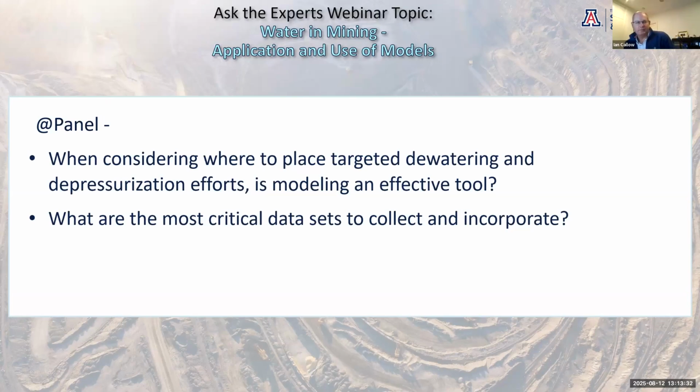Well, from my perspective, it really comes back to the conceptualization, right? Which I know Jeremy and Jeff are very keen on. But without that conceptual model, it's a bit blind. And so the data sets, in my mind, are very much the structural model, and any monitoring wells, piezometers you have around that, and their responses will dictate just how effective your depressurization efforts are and where to target next.